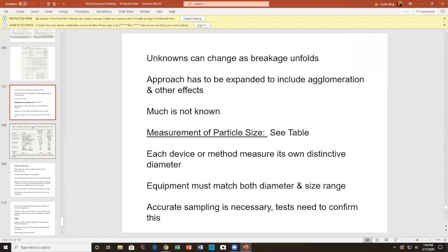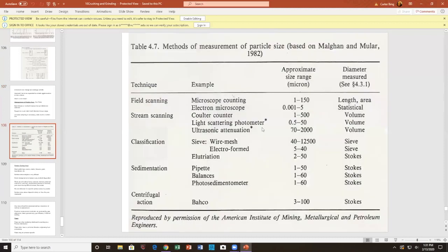What's interesting, and maybe I've told you this, is that there's a Stokes drag regime and then there's a fully turbulent regime. You quickly see that particle size measurements are actually broken up. You have the Stokes diameters, and then up here you have the more turbulent diameters.